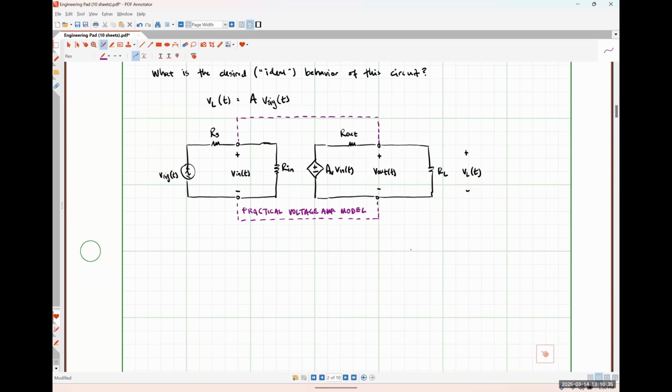We talked about it having a non-inverting input terminal and an inverting input terminal back in circuits 1, but it only has a single output terminal. So that's why it's a single-ended output differential amplifier. So we actually have to very slightly modify our practical voltage amplifier to work for op amps because we have multiple input signals, okay?